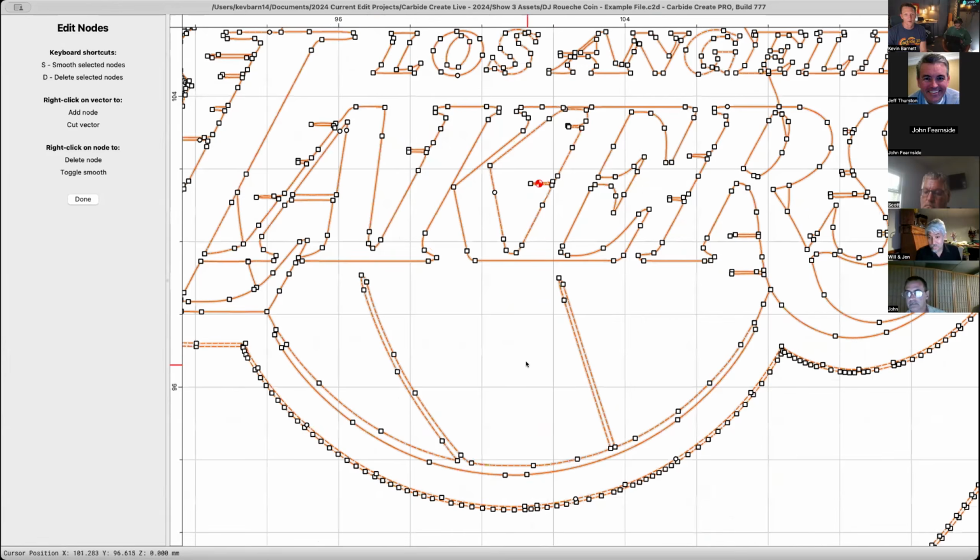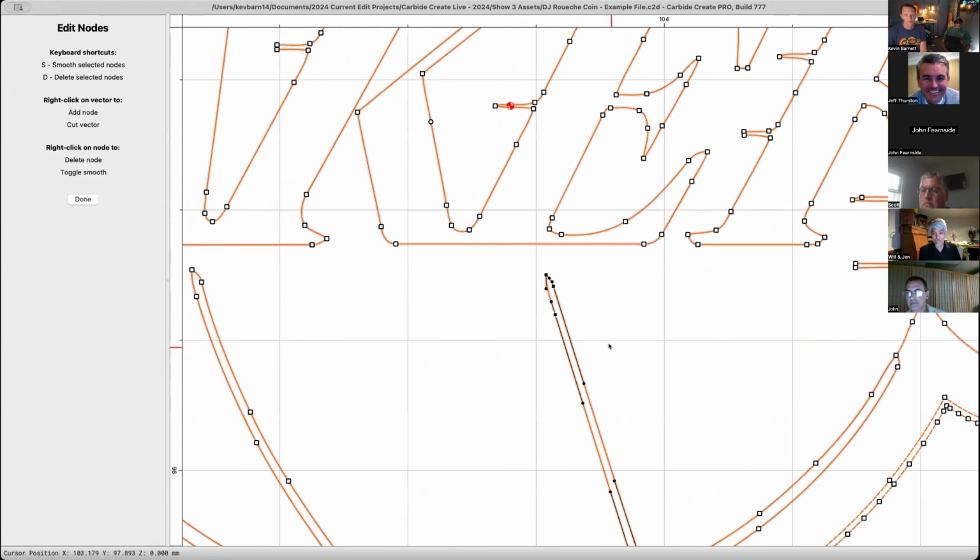Once I'm inside the node editor, I'll use two more hotkeys a bunch. You can highlight a node and hit smooth and unsmooth so that it either becomes a right-hand turn or straight lines, or it adds some smoothing to it. And you can utilize the arms to adjust. Smooth and unsmooth works quite well when you're trying to fine-tune an object.